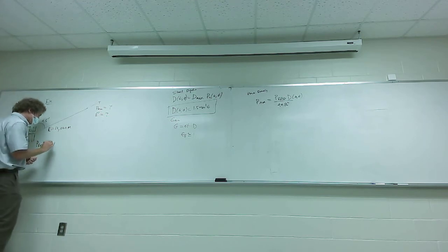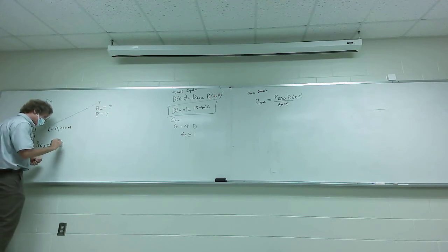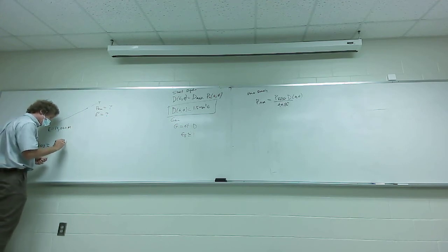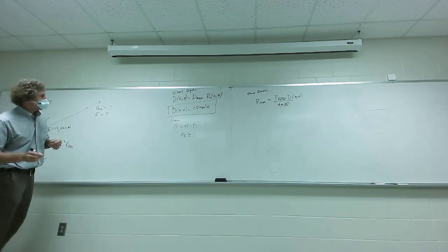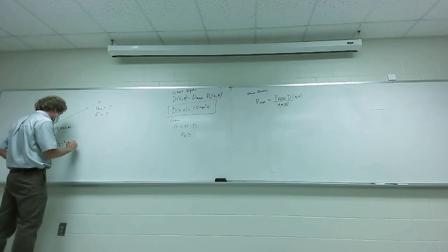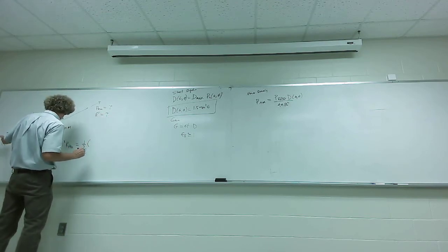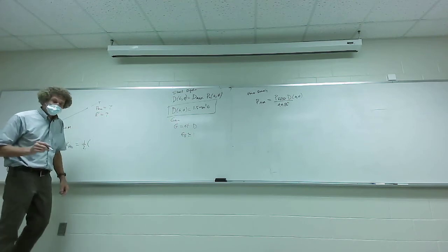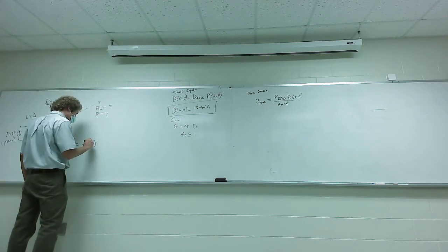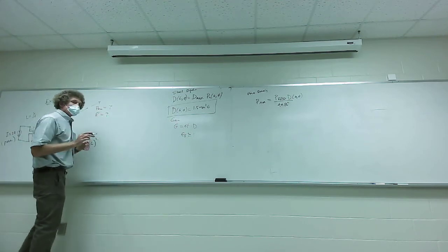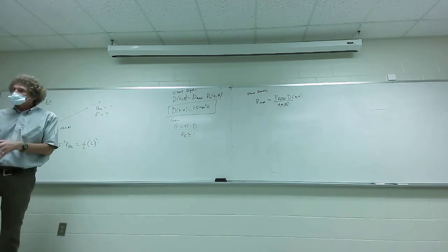So P rad is equal to 1/2 the magnitude of I squared times R rad. Do you all see I put down I as 2 here, class? It's 2 squared times R rad. Some people are going to say, do we have to memorize R rad?